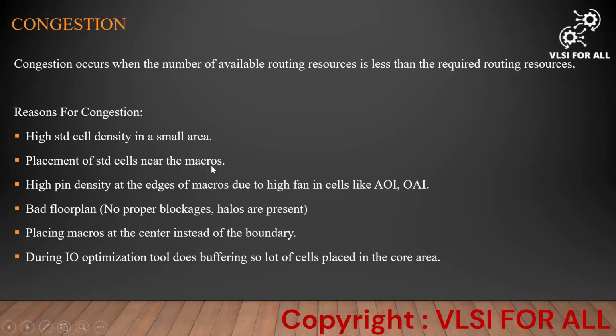Placement of standard cells near the macros. If more cells are placed near or around the macro, it will cause congestion, because they have connections, and again during routing it will cause congestion. Also, at the macro corner areas, if any OAI cells have been placed, these special cells have more pins, so it will cause more pin density. That is also one kind of reason for congestion.